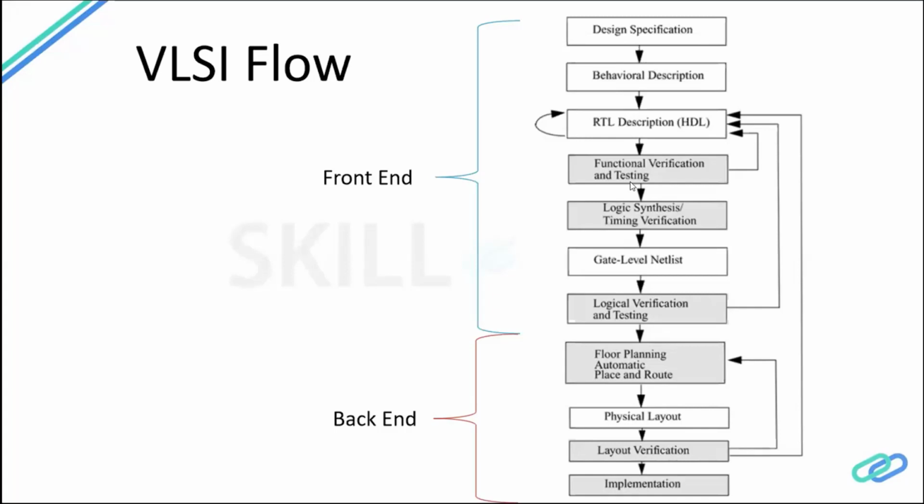So when we say that our design is tested completely, there are a few parameters based on which we verify that. And in this stage itself, we have a few checks on the design aspect, something like linting. I'll go into details on linting in the next few slides. So we do some checks called linting checks. We do clock domain crossing checks. And we do logic synthesis, that is, synthesizing the design into netlist format.